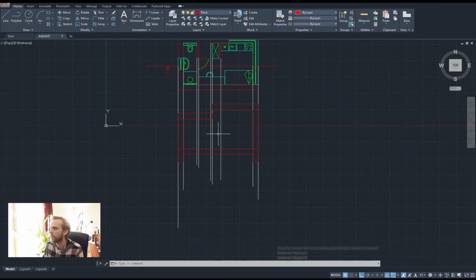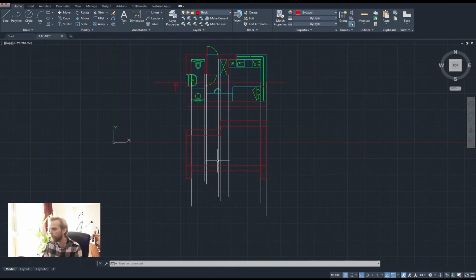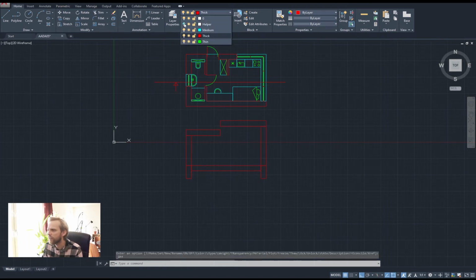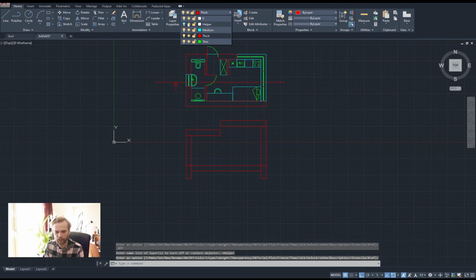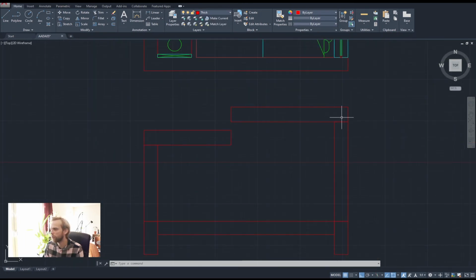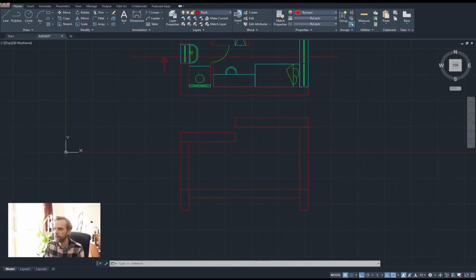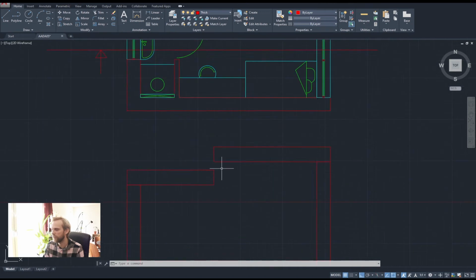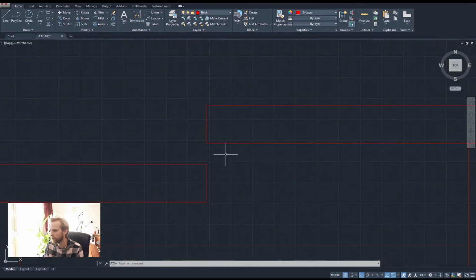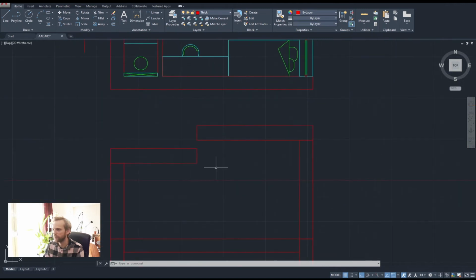Okay, that is done. Now, I kind of want to clean everything up, right? So I will hide the helper layer for just a tiny bit. And I want to join everything up into one big happy family. And also one more thing I want to do is add a wall segment right here, because these two roofs need to connect, right?